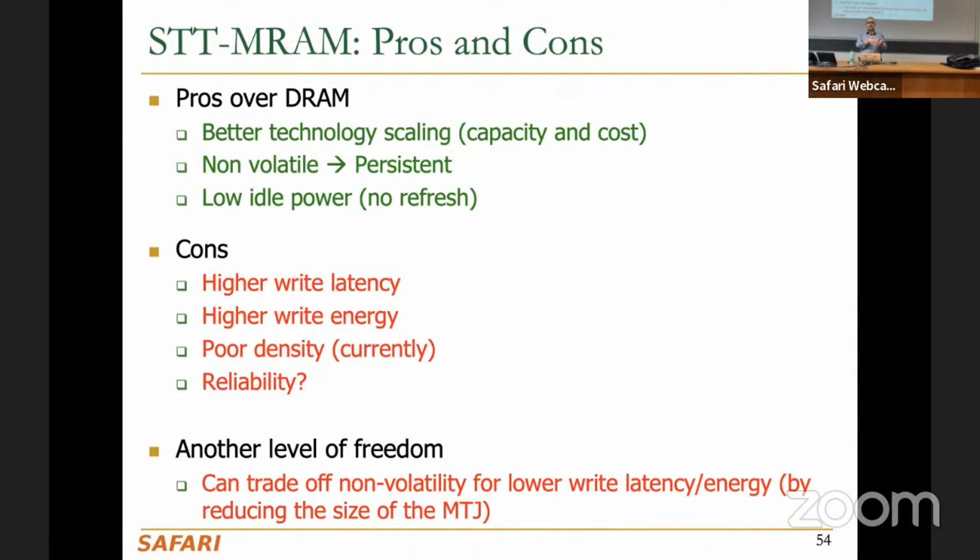Unfortunately, STT-MRAM is not as dense as DRAM. Its density is very similar to SRAM. So that's why people also look into how they can use STT-MRAM and SRAM together, and they design different architectures like caches for GPU, CPU, and other devices. But in this work, we are discussing how we can use STT-MRAM as a replacement for DRAM.